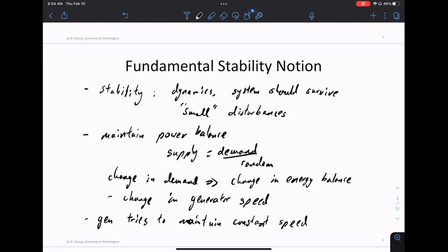In Texas, if you look at last year's blackout during winter, the reason they had a blackout or rolling blackout was trying to make sure the frequency in the system is correct. The frequency in the system, the generator speed, is the global indicator of how stable a system is. But that is an indirect measurement of the supply and demand imbalance. So that's our goal.